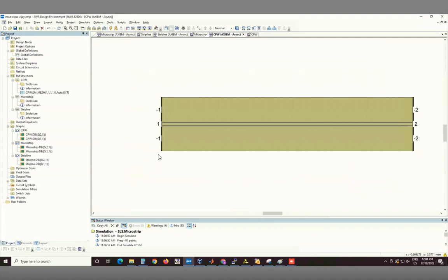Now there are many other factors, right? Whether you have measured correctly. Second is whether the dimensions you have actually tried to design have come out correctly or not, because there are tolerances in the machines which make this. But again, if you're talking about agreement in the level of below minus 20 dB reflection, that has really no meaning because the errors will propagate very easily, especially if you don't calibrate these instruments. So there is another calibration step.